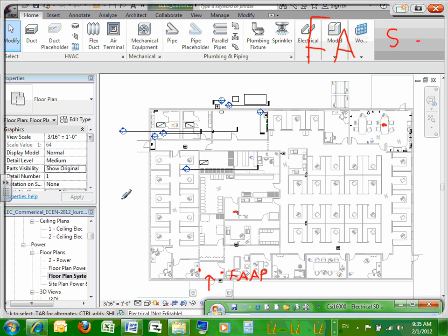But in this building, we have responsible adults working here for the most part. So we want fire pull stations at every exterior door. You got one there. You got one there. You got one here. And you probably got one in the receiving room here also.